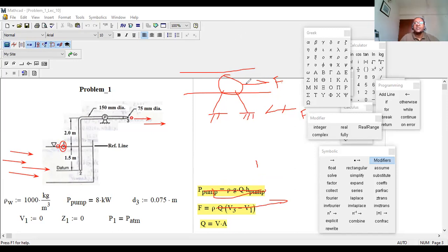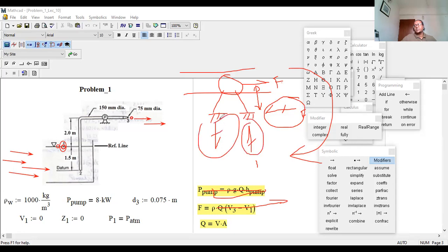Look carefully. This is interesting. Your force is working along this direction, so the support works at the bottom. How much is the height between this distance? This much. So there will be a rotation, right? The moment is working along this direction. That means it will try to rotate your support clockwise. That means this support will experience a force in the upward direction, and this support in the downward direction. So you have to put a reaction force over here and over here. So you see the support will experience two forces, this force and also some vertical force. Okay. Anyway, you got your answer, right?